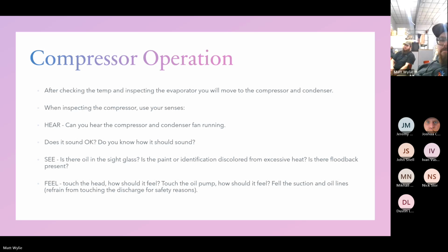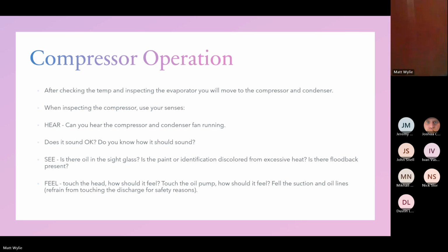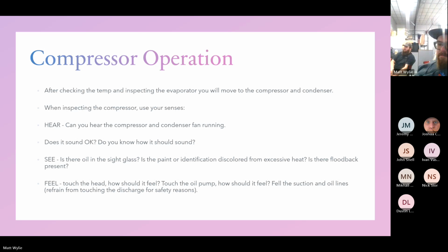So obviously the terminal with the lowest amount of resistance is going to be your common, your start is going to be the highest, and your run is going to be the middle one, I believe. Correct me if I'm wrong, but that's how I've been doing it, and it's been working. When you're checking resistance, though, you're usually checking across 2 terminals, right? Yeah. So how do you determine which one's the highest when you're going across 2 terminals? Well, you would have to do them in pairs, right? Once you do 1 to 2, 2 to 3, 1 to 3, you'll see what your lowest one is, and then you find your highest and your middle, which would be your start and your run.